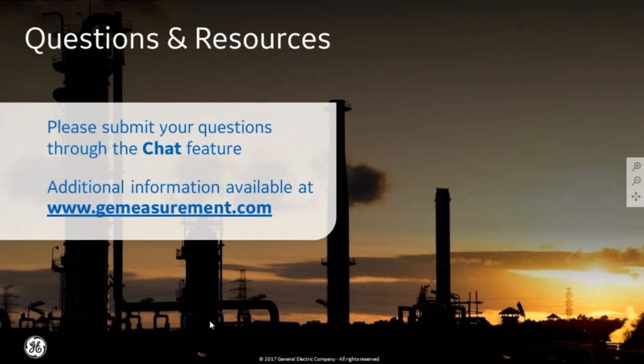Okay. And then a question about during the TCG calibration, why there is no TCG curve on the A scan. The short answer is that feature has not yet been implemented in the instrument. Again, coming in 2.0, especially on the conventional channel side, there's been a lot of work done around amplitude evaluation techniques. DAC and TCG are going to be available there. They are displayed on the A scan during work. The utility of the TCG line displayed on the A scan hasn't been felt to be quite as prominent on the phased array side. That's certainly something we can add in future releases, but it just wasn't a high enough priority yet to be implemented.